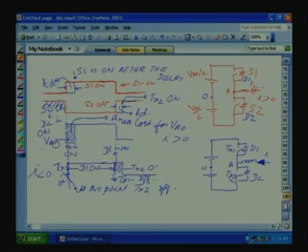So, if you see here, when the D1 is conducting, because of the dead time, the VS0, this much area is gained. Area gained, that is volt second, area gained for VS0. So, what happened? It can affect the fundamental. How it can affect? Let us go to the next page.